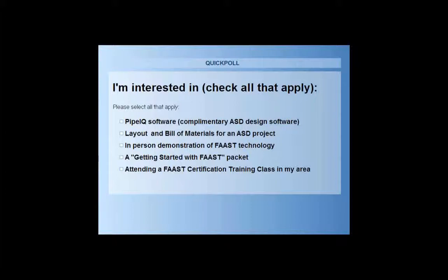They're talking about the beam application, and are they saying should we recommend, or let's see, are we testing at the bottom of the beam, or do we go up into the beam pockets? When we design them, we do both. Okay. We do both. You're not adding any more cost to the device, right? It's not like spot type detectors where you need to put one in every location below the beam in that beam pocket. It's one device. It's the same FAAST detector, depending on obviously the size of that. Then it's just a matter of installing holes. So we do call out for below the pockets as well. Okay. So in the pocket and below the pockets.